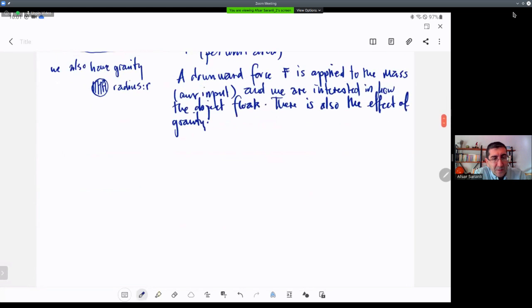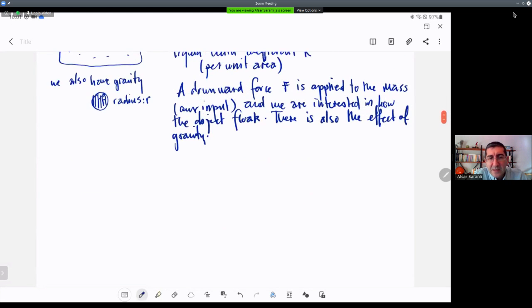In mechanical systems, right, the biggest thing is the free body diagram. In the free body diagram, you have to assume directions for the forces, for example, the friction force, right? Often what we do is that the frictional force is in the reverse direction of the motion. Okay, and if you take that kind of a direction as your default direction, the frictional force will come out to be positive.